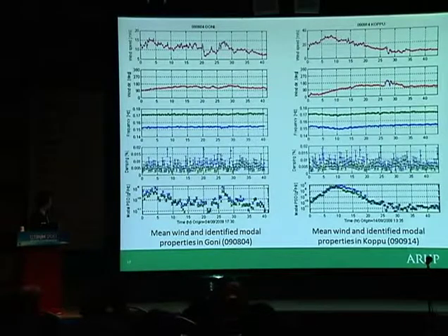It shows the damping ratio versus the time history of the typhoon. So you can see the variation of damping. For every single point, you have a most probable value, and also you have a variation of this damping with time. So all these numbers are calculated in half-hour non-overlapping windows.